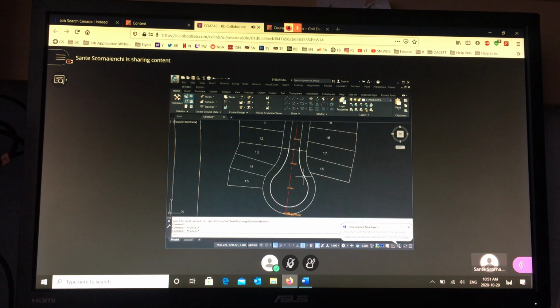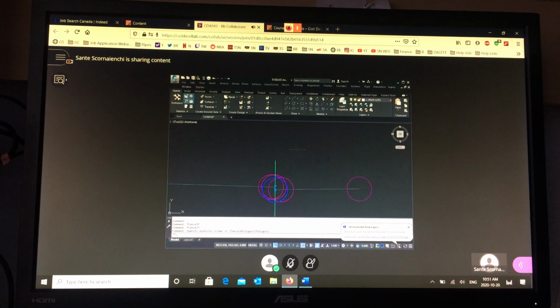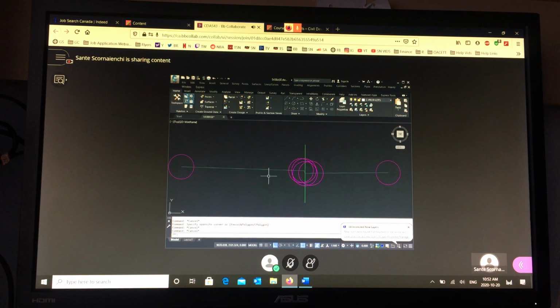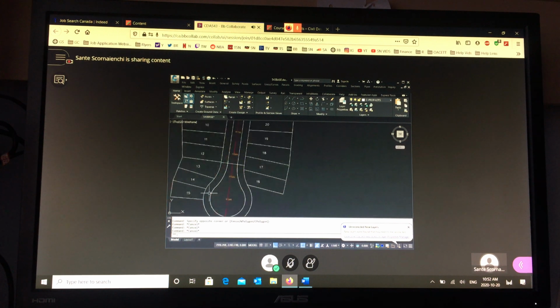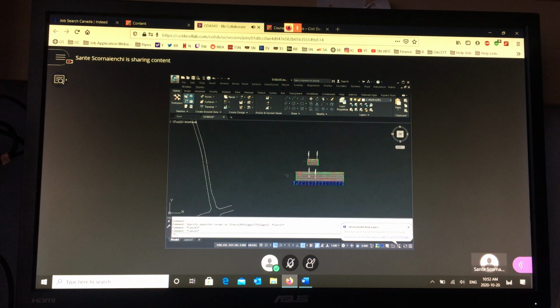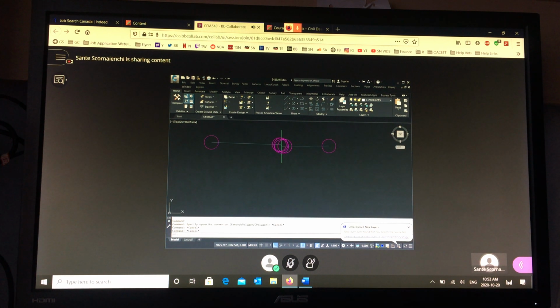Now, because I want to reuse this assembly with subassemblies, I want to make sure that my alignment is oriented so that the boulevard is still on the left side. So to do that, I want to make sure that when I create an alignment from this polyline, 0 is on this side, so that when I come around, this is the boulevard side. Okay? If I put 0 on this side, that's not wrong, but if you do that, then you need to create the mirror. You have to create this with a boulevard on the right side. Okay, so that's the difference.